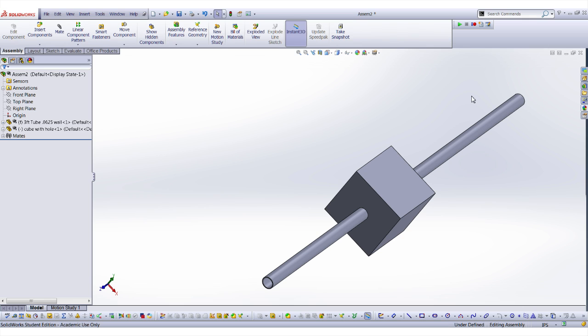How do you insert the cube into the... The cube. Insert part in the assembly tab. So go ahead and exit out of mate and everything because you don't want to be mating right now. Exit. Yeah, assembly. Insert component. And then there's your cube right there. You can just click on it and then mouse it up. Click. And then you can do the mate thing that I just did. You can click on those two.